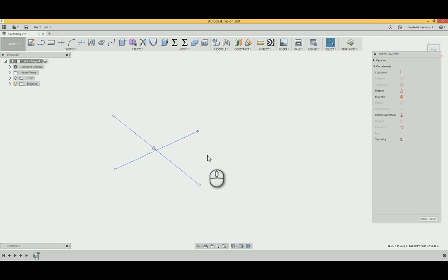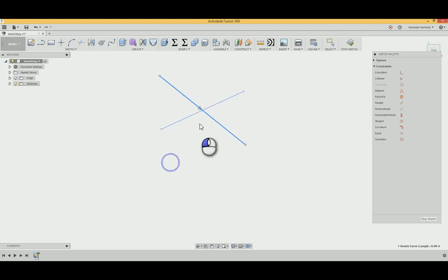They still have some kind of degree of freedom that they can move or bend to. And if you're designing something, you don't want any blue lines, okay? Like on your finished sketch. They should all turn black. There are different ways to do that, but we'll get to that. What I want to do is, you'll notice this thing just kind of moves all over. We're going to do the next constraint.